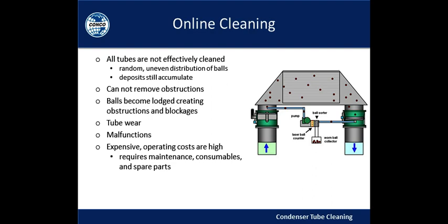In fact, balls may become hung up on deposits and obstructions. Well, look, the balls are designed to travel through the tubes at random, right? So there may be an uneven distribution of the balls. Deposits will accumulate.